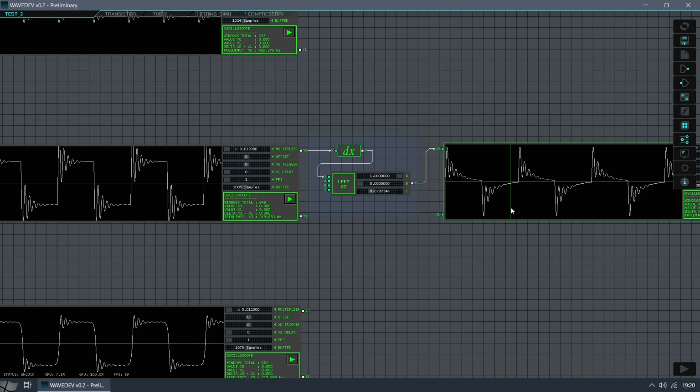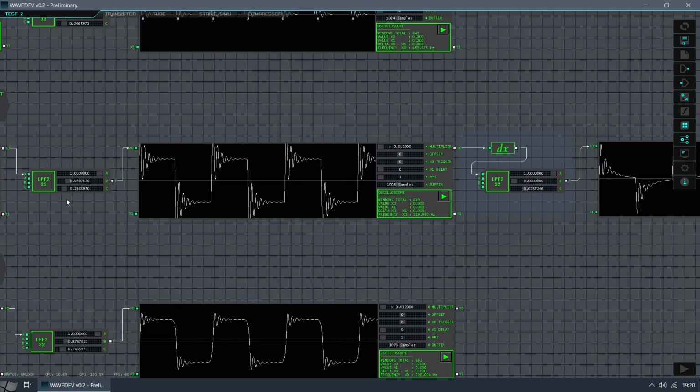This is a typical wave pattern of the pseudo-square sample captured after passing through many systems. With the systems, I mean an amplifier, cabinet, microphone, and even the acoustic characteristics of the environment. All these factors add some color to the sound that finally reaches our ears. With the resonant filters, we have control of this coloration even before the signal comes out of the speaker. So we can sound good without relying so much on the external equipment that accompanies a distortion. This is, in my opinion, where the digital world will dominate in almost all aspects.